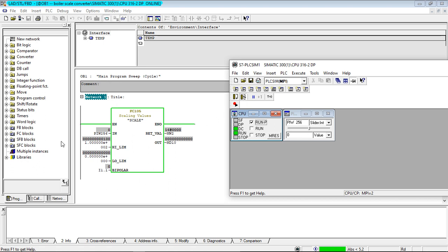So I want you to look at, since the input is on 0 now, the current value is 0. Just watch as I increase this slider. Can you see? This is the raw data coming from the feed. But if you want to equate this data to the current temperature of your boiler, that means your current temperature of your boiler is 28.215 till you get to, you see, so that's how to convert your analog signal.